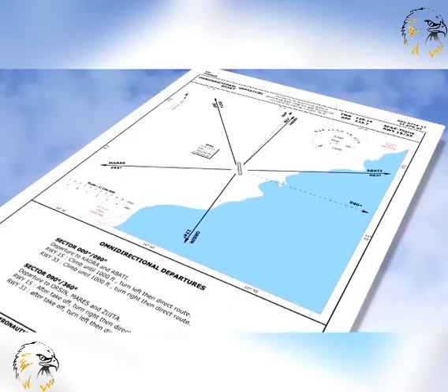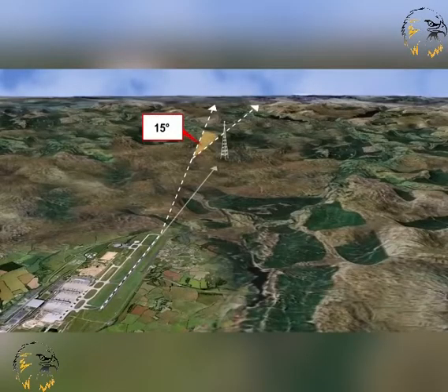Where no suitable navigation aid is available that can provide specific departure track guidance, then the criteria for omnidirectional departure plates are defined. Wherever possible, a straight departure will be specified which is aligned with the runway. If, to avoid an obstacle, a turn of more than 15 degrees is required, a turning departure is constructed.